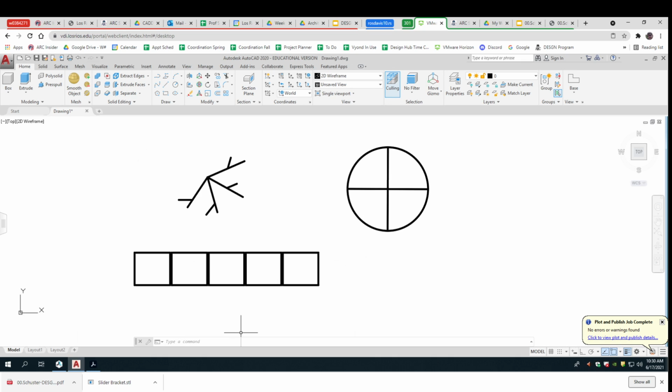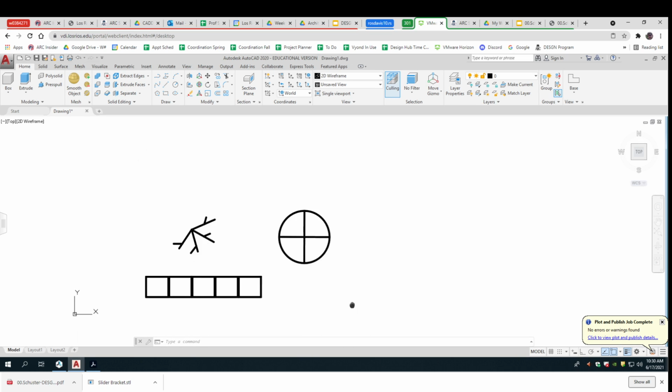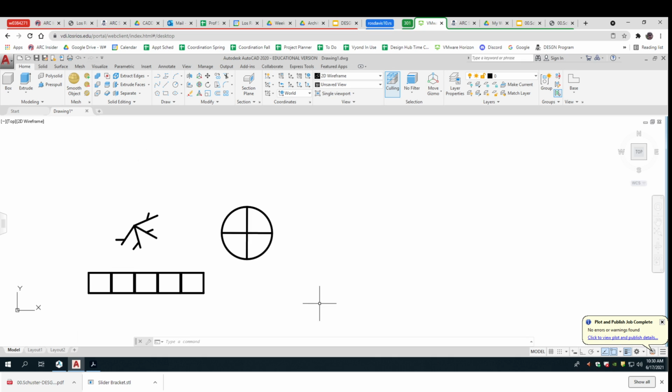I have one quick question. Yeah. Differences between line and polyline. I end up using polyline most of the time. Yeah. The difference between line and polyline is polyline is far more powerful, but you have to know that if you want to do something to just one segment, you have to explode it.